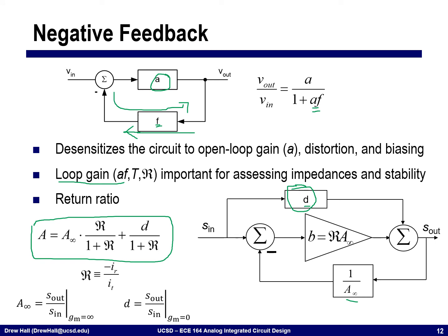In order to get each of these individual components, we simply analyze the circuit. For the return ratio or the loop gain, we take a transconductor, we cut the circuit at that transconductor, insert a test source of the same type, and then look at how much is returned back at the source.